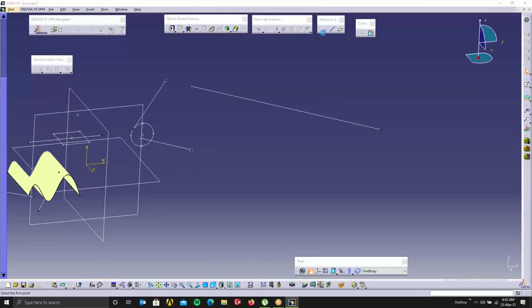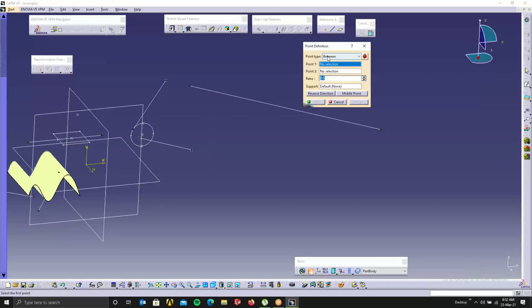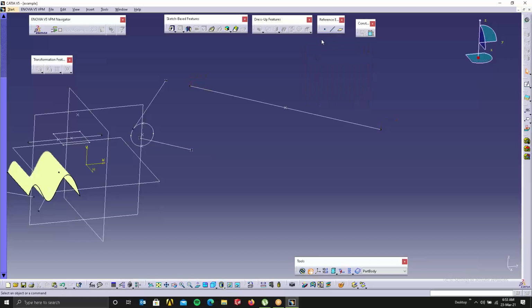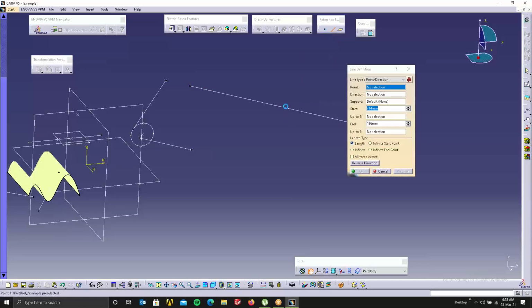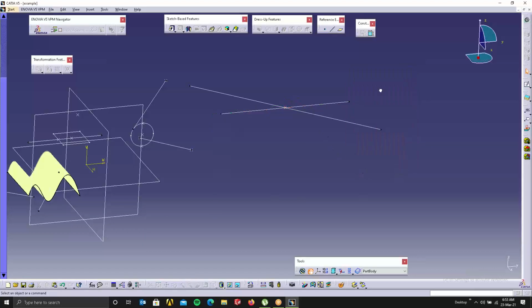So for example, what I'll do is I'll just take between. Okay, these are points. So I'm taking this endpoint and this endpoint. Okay, so I'll take the 0.5 middle point. I got one. So I'm taking line, point, and direction. I'm selecting this point. I'm giving some direction to it, x-axis or y-axis. I'll give y-axis. I'll click OK. So here it's intersecting at this point.